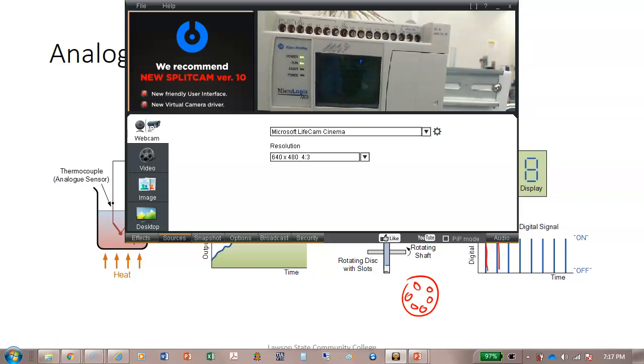The Siemens PLCs that we'll deal with in ILT 212 has a 12-bit A to D converter in it, which means it can take a 10 volt input, and divide that into 4,096 different combinations. So that has a better resolution, but sooner or later we're going to have to give up on the number of combinations we have. So digital is no way in the world can be as accurate as analog, because analog allows us to deal with infinity. We can't deal with it, but analog can.